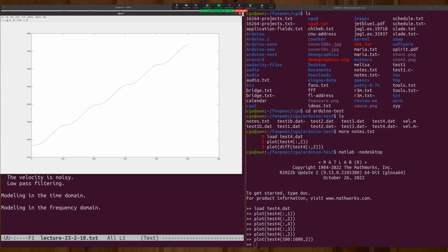Now, that unfortunately doesn't tell you which way the thing is moving. So the next thing you do is you put in a second photodiode, slightly offset from the first one. And then when a pulse comes in this way, one of the photodiodes is activated first and then the other one.